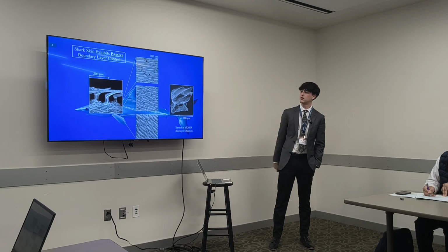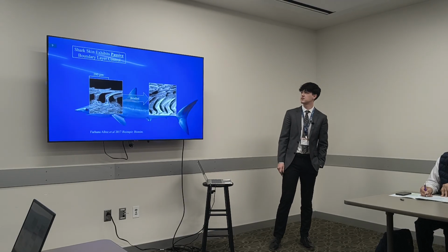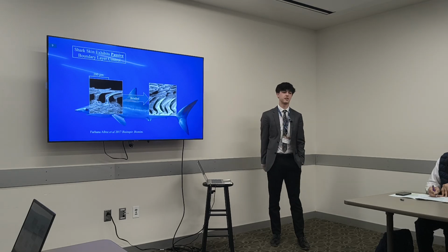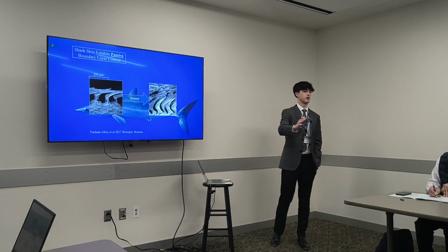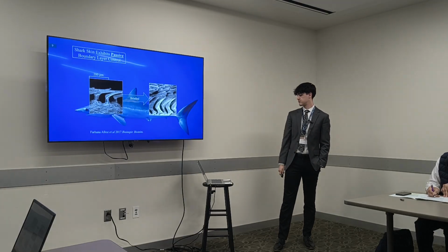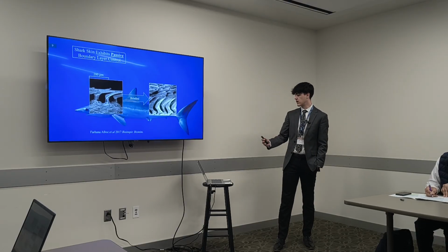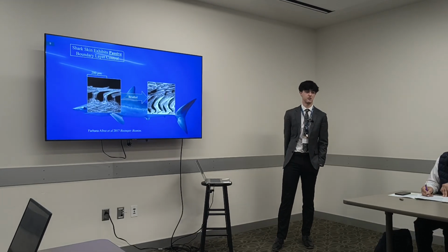And then here's more of a cross-sectional view of those shark denticles. And what happens is how they passively control a boundary layer is they become bristled as the shark continues to swim in the water. And so what happens is that that increased angle upward actually catches that pressure reversal and therefore makes it even more hydrodynamic.